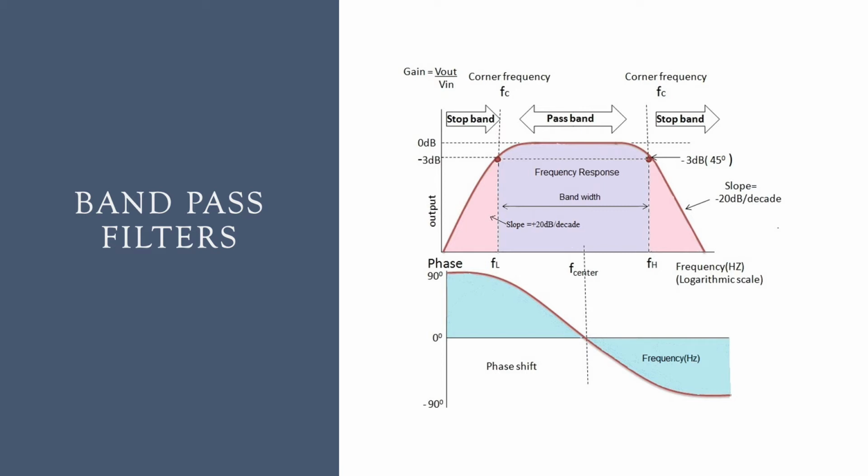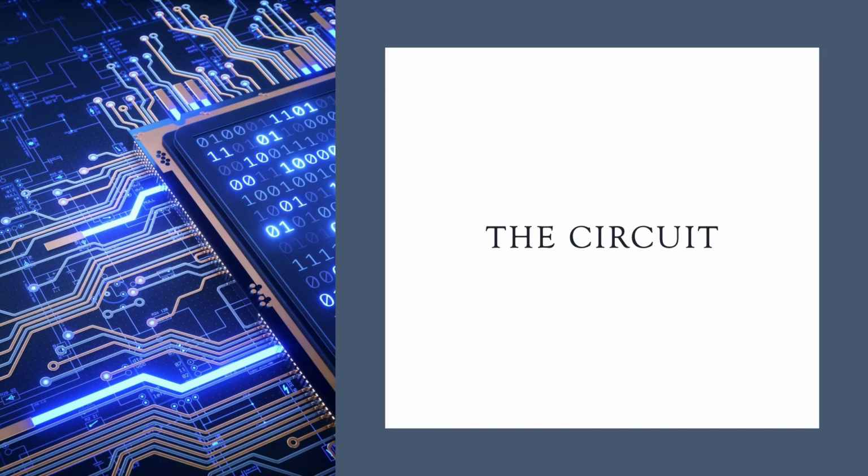This type of circuit is ideal for situations where very high frequencies and very low frequencies are not desired in the output signal. For this circuit, we need to separate the high and low frequency components of the input signal. The high frequency part of the input signal will be sent to the mid-range speaker. The low frequency components will be sent to the subwoofer.